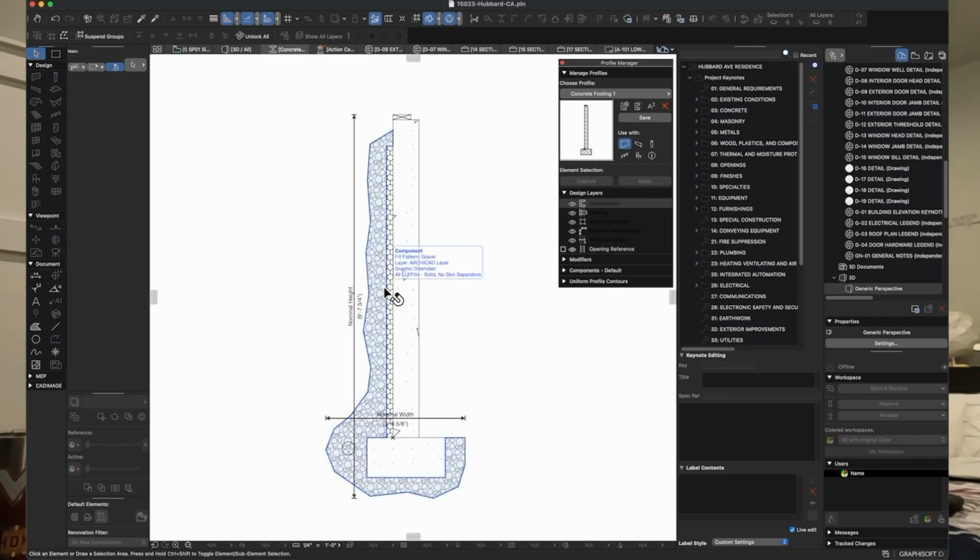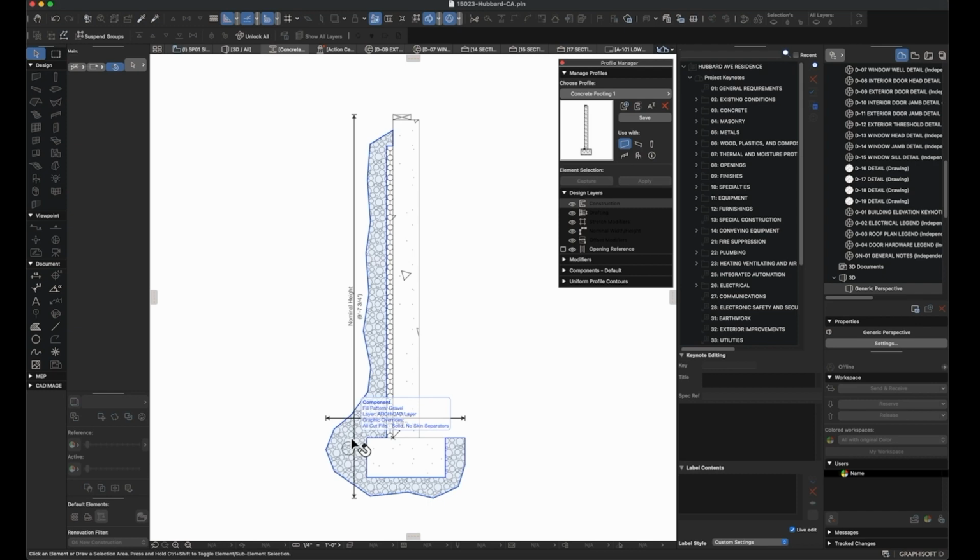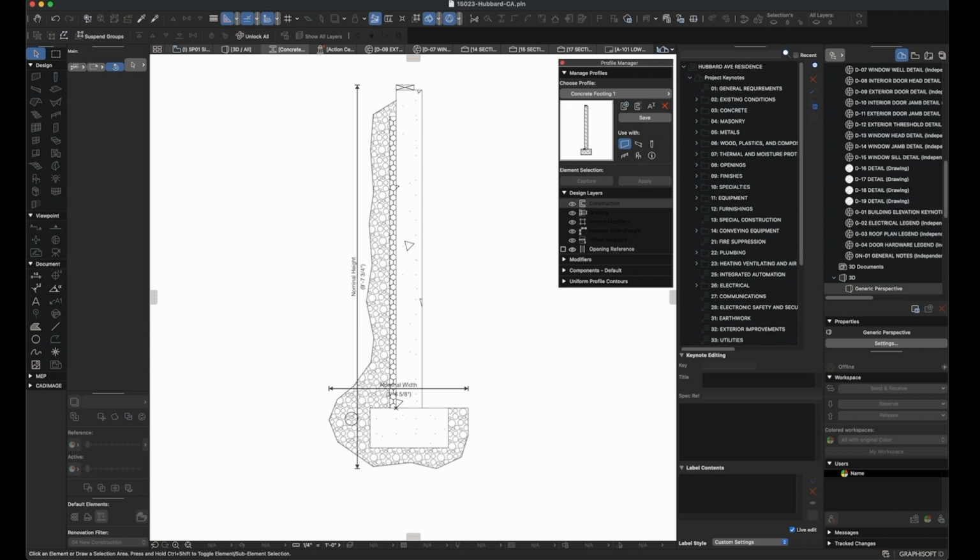And water is going to go the easiest path out. Well, what's easier than an open pipe? The perforated pipe basically creates a conduit for the foundation drain because it's perforated, but it allows that water in. Because it's an easier path, the water will tend to flow through it. Then this gets connected to another pipe that can convey it to another area of the lot or even into a stormwater system.